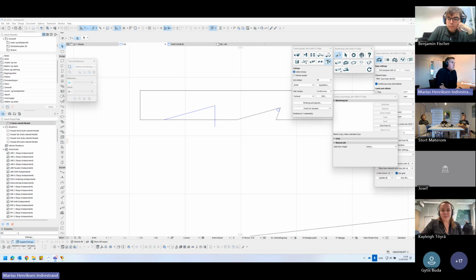As I'm not a Hundegger operator or anything, I just use the tools, or we set up the how-tos here at Støren based on the feedback from the factory. So for us, it's best to use the groove tool. Our Hundegger operators like to use the saw blade for this type of cut. Okay. So it depends a little bit on the production line, the way the machinery is set up, basically.